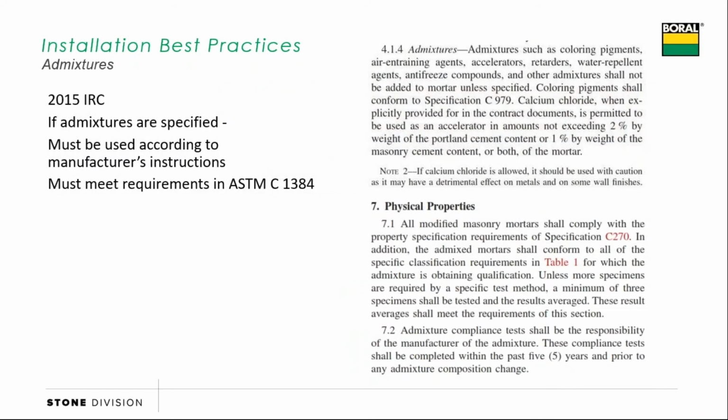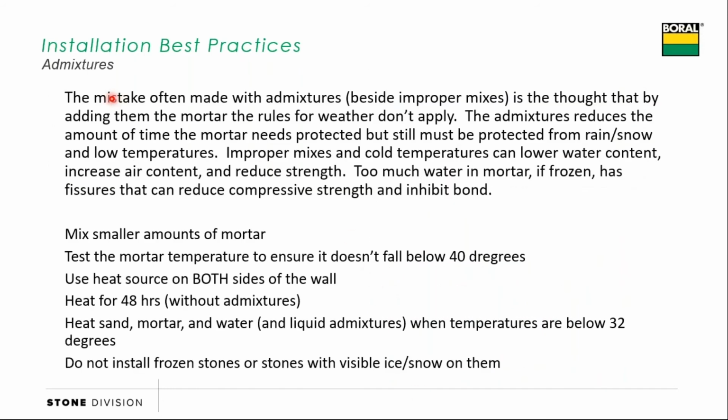If you need to use some type of an admixture, cold weather application where we're trying to accelerate drying time, or hot weather where we're trying to slow it, we're not big fans of the different admixtures, but if you have to use it, just make sure you follow that manufacturer's recommendations for how much diluted and when it's used. The caution around cold weather is those admixtures do not lower the freezing temperature of your mortar. All they do is accelerate the drying time.